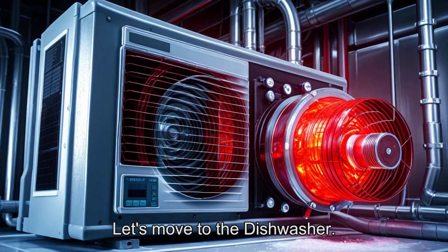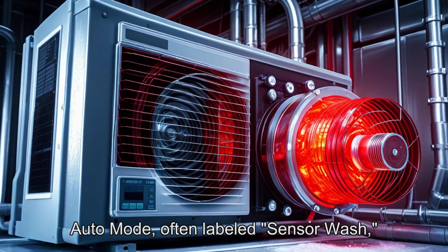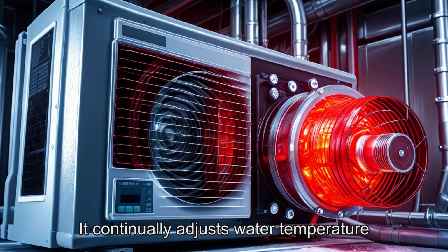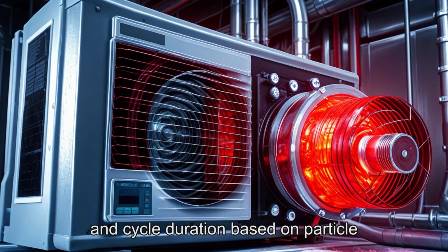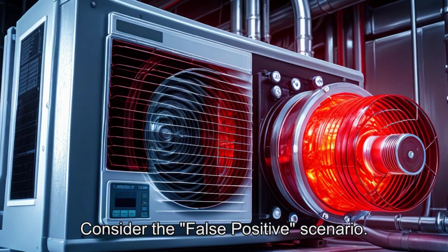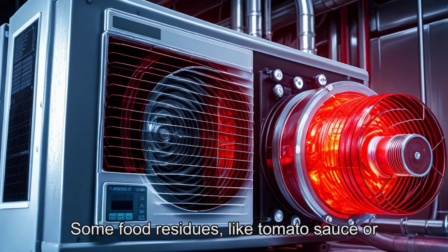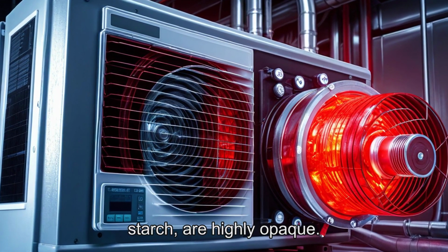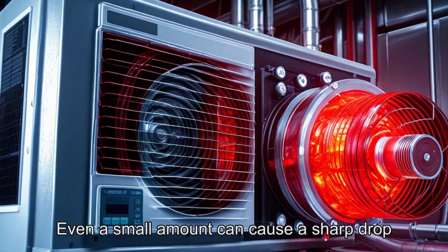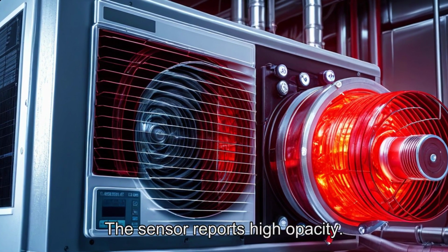Let's move to the dishwasher. Auto mode, often labeled sensor wash, uses a similar optical analysis. It continually adjusts water temperature and cycle duration based on particle detection. Consider the false positive scenario. Some food residues, like tomato sauce or starch, are highly opaque. Even a small amount can cause a sharp drop in sensor readings. The sensor reports high opacity.